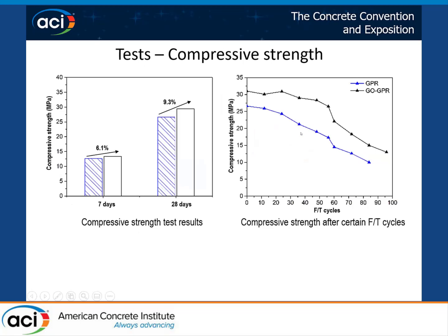And we tested the compressive strength of these two binders. The graphene oxide did improve the strength, but the increase ratio is lower than many ratios reported by other researchers. The main reason might be the difference in the matrix, and the many electrolyte activators may also affect the function of graphene oxide.